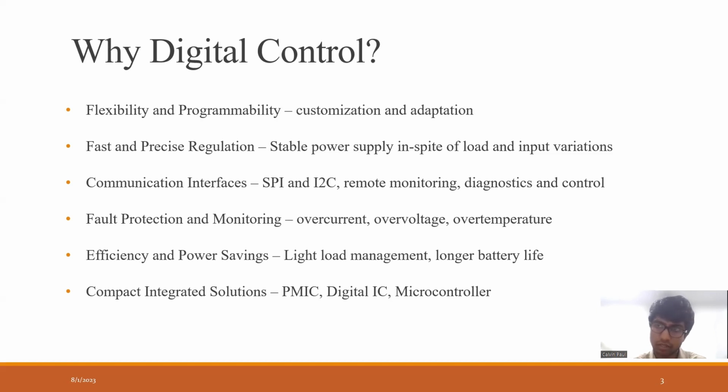One is, suppose you want a resistance of 1.9 kilo-ohm, but in the market you might not get a resistance of 1.9 kilo-ohm. There might be 1 kilo-ohm, maybe 100 ohm, but exactly 1.9 kilo-ohm might not be available. Similarly, capacitances. You might want a capacitance of say 65 microfarad, but in the market you might get 47 microfarad, 100 microfarad. So you might not get the value which you exactly want. Another aspect of these passive circuits is that they age over time. The values of these RC parameters might change, so it degrades over time.